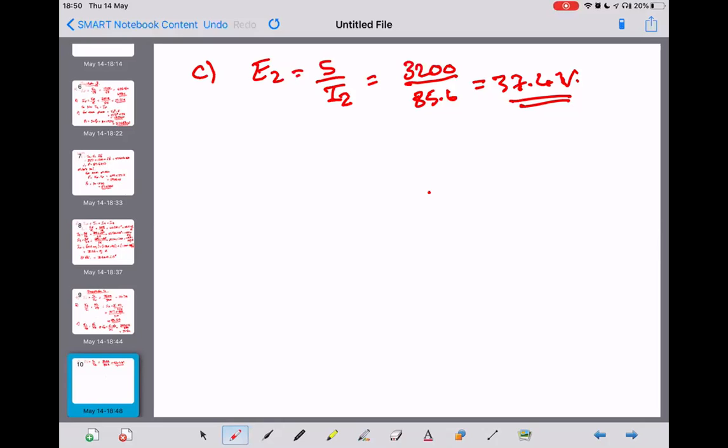You can't get more power out than you put in. You certainly don't really want to get less. So that 3200 VA applies to both the primary and the secondary. Again, that doesn't matter. You've got the right answer, so it doesn't make any difference that you've done it that way. We're just trying to get across that the S is the same for both sides.